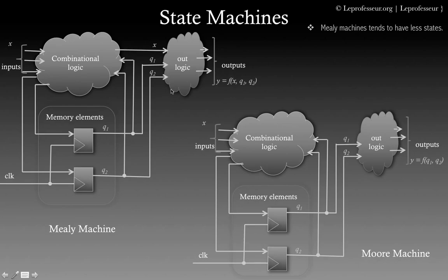Now that implication goes on to timing as well, because if you are going to use more flops, that will have an impact on timing, a bit slower circuit compared to your combinatorial block, combinatorial logic. So basically, if you are using all combinatorial blocks, you can just get the output on the next clock edge. But with the memory elements, you have to check, because a flop produces output, and you can make use of that output only in the next clock edge. So there is a little implication there.